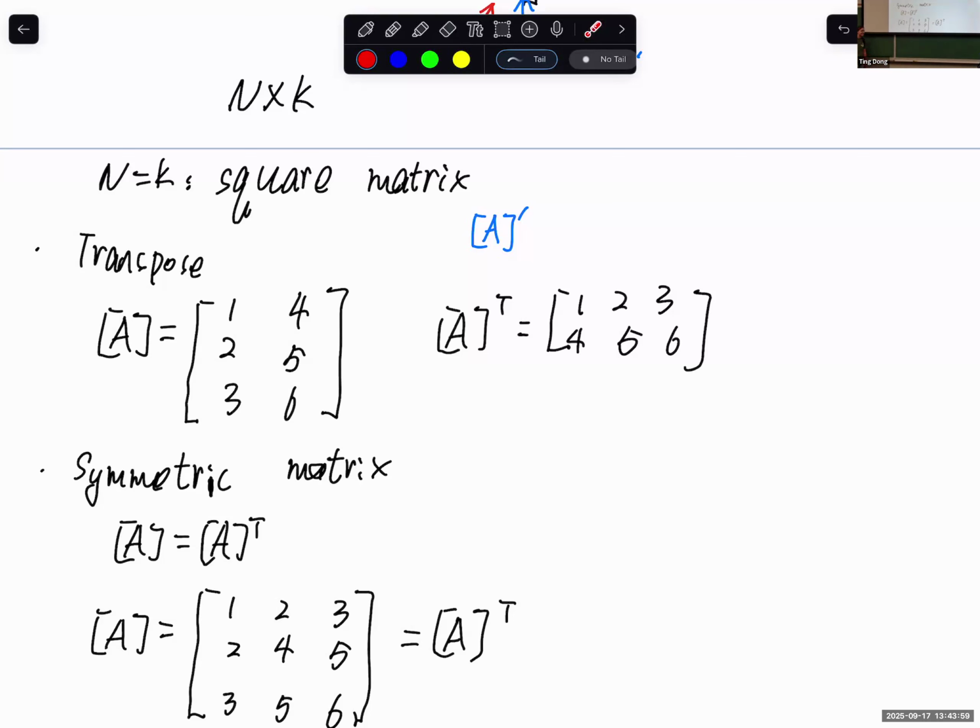I did the element matrix for this, trying to keep it the same way. When I'm putting it together in the global matrix, I was wondering which of the rows and columns have to be removed. I see 2 and 3 are boundary conditions. Yes, everything related to 2 and 3 is 0. So all the rows and columns corresponding to 2 and 3? Yes, you only have a 2x2 left, only U1, V1, 4 components left. Then I just continue from there. Thank you so much.